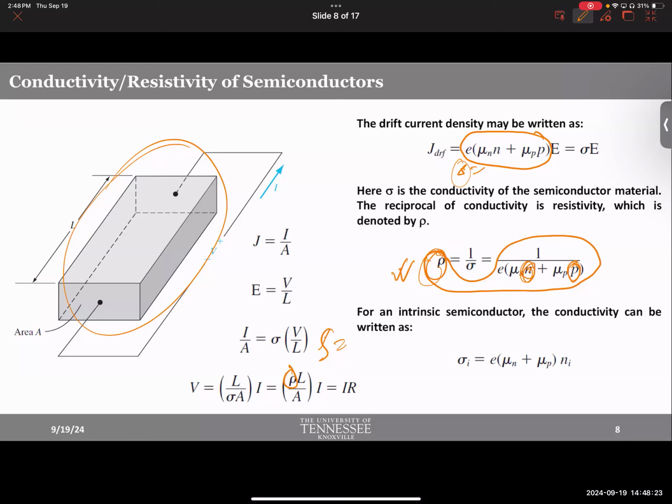The challenge lies in dynamic tuning. There is a difference between dynamically changing the resistivity, meaning while you are using a certain device, you have already made the device. You have already used a metal. Now, if you want to change the resistance, are you going to go and change the metal there in the device or the circuit? Is it possible in an integrated circuit? No. But imagine if you had a material whose resistivity could change during the usage time. Like while you're using it, by applying a voltage, if you could modulate the resistance, that would be fantastic.